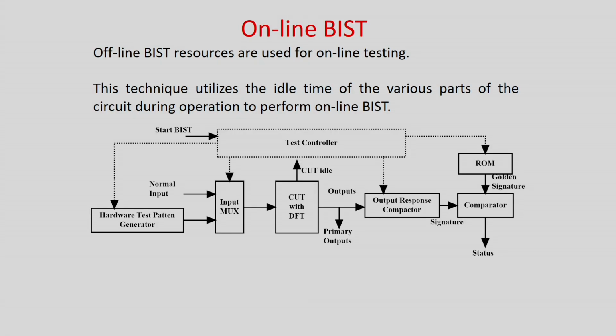Last but not the least, somebody had tried to use BIST for online testing. What is the idea? This is the simple BIST architecture I have explained so many times in the last few lectures, I am not going to go over it again, but a very important line here is called the circuit is idle. BIST is always applied when the circuit is starting up. So you know that there is a normal input and there is a test pattern generator and there is a mask. When you want to apply the BIST, this input will be cut and the circuit tester input will be coming from the LFSR or some pattern generator. I will elaborate on the details when we are discussing BIST.